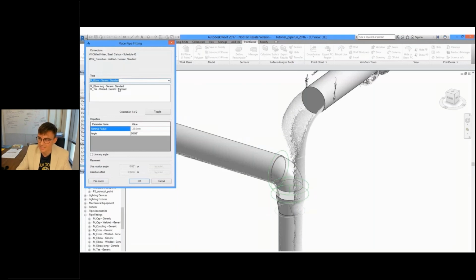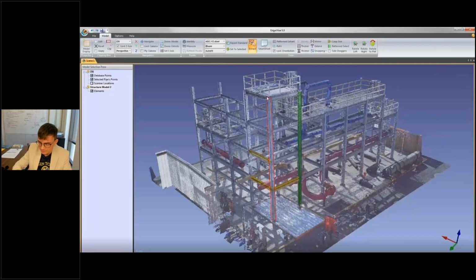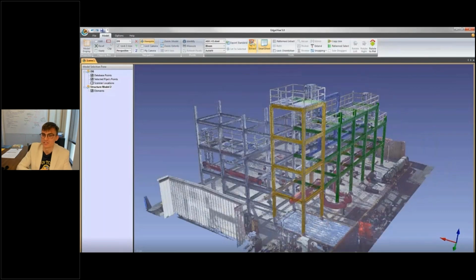Semi-automated is where you click on some region within the point cloud and the software will fit primitive geometry to those points. Or you can identify a component, like one of the columns here, and define it as a template or a pattern. And then the software searches the point cloud looking for things that match that pattern. We're limited to semi-automated here because it's impossible to search for every conceivable kind of component. And there's also ambiguity between things like two back-to-back angles and a T. So it's easier if you just give the software the hint.